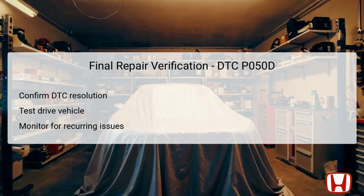have been cleared. Following this, a test drive of the vehicle is crucial to validate that the engine starts smoothly and maintains a stable idle, particularly during cold starts. During the test drive, pay close attention to symptoms such as idle stability and engine response under various conditions. After the drive, continue monitoring for recurring issues or any new codes that may indicate underlying problems.